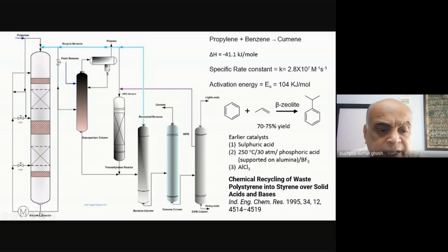And then I'm taking out the alkylated product from the bottom. It has several catalytic beds, like we have seen in so many cases where you have multiple beds. And then what you do is there's an excess of propene, so you recover the propene, and that's recycled back. And from the bottom, you'll take out your alkylated product.